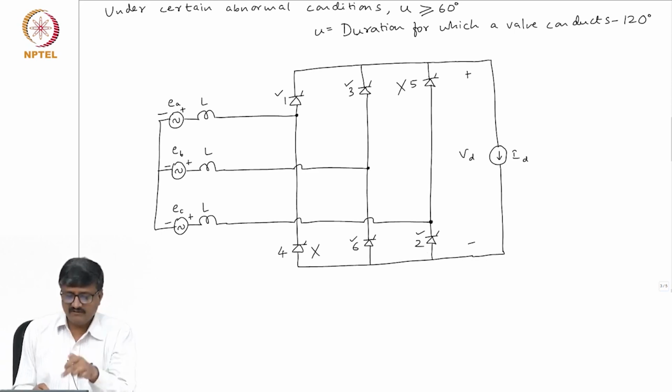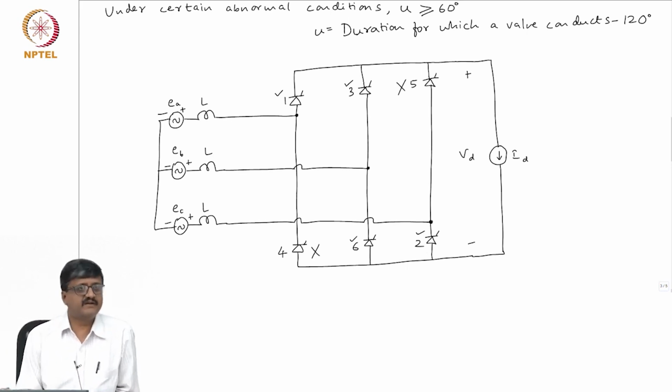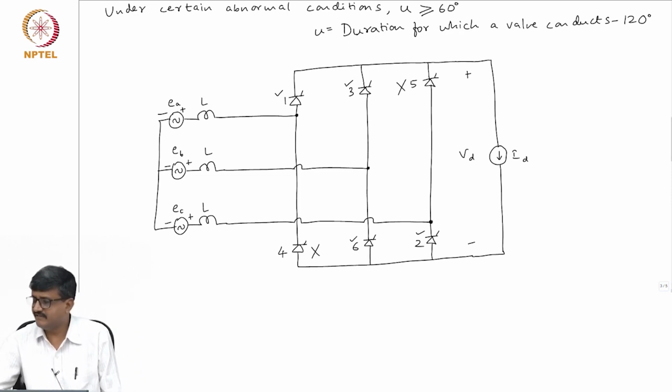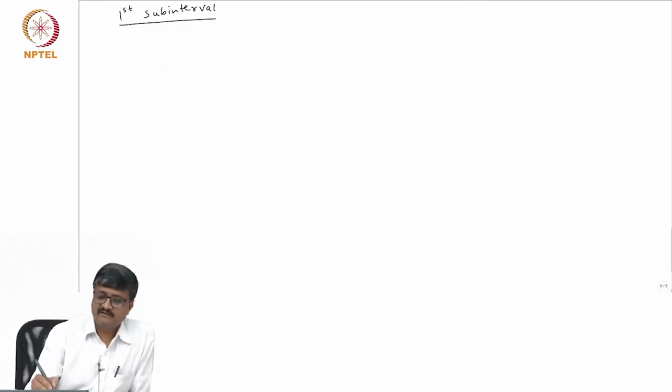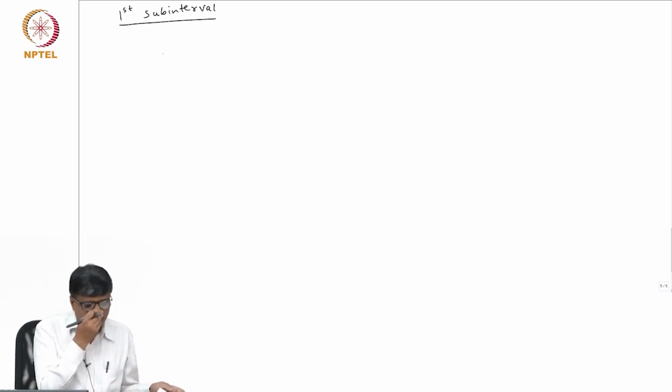Okay. So, all the 3 sources and the inductances connected in series with the sources are conducting, the 3 voltage sources. So, the revised circuit which shows only the elements that conduct current is drawn next. So, I will redraw the same circuit without showing the 2 thyristor valves 4 and 5.